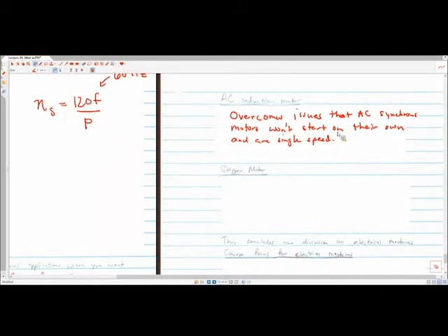So the rotor, like in every other case we either had rotors that are composed of coils for electromagnets, or they were permanent magnets on the rotors. This is considerably more simple than all that. This is just a cage-like structure, and it's made of some sort of electrically conducting material. That's it. That's all there is to it. And so then you have the ability to form loops, such that you have current to flow into this one, and then say out this one. Right? So you're just creating these conduits for current to flow, and it's going to be flowed back because of back EMF and Faraday's law, and you're going to get force from Lorentz law.